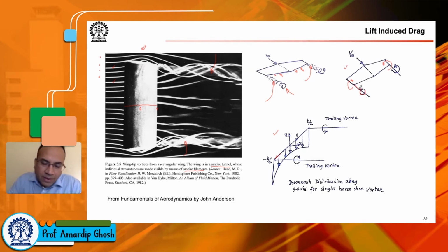I have a slide that talks about what is a vortex line, what is a vortex tube, what is a vortex filament. And here, essentially, these two lines, technically speaking, are the vortex filaments. However, what is important is that the strength of the filament is the same as the strength of these contrails. When we say strength of a vortex filament, we are essentially talking about the circulation developed by the vortex filament or the vortex tube. So here we are replacing these with two vortex filaments whose circulations are the same as the circulation developed by these contrails. Okay, that's how we model from the real to something that is more amenable to analytical description.